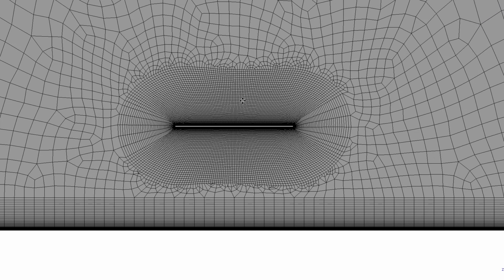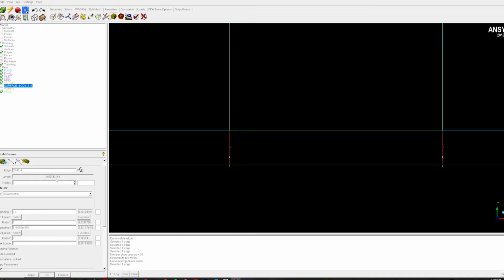identical setups. Initially, the project was using ANSYS native meshing, like with the smooth plate. With the smooth plate, this is fine on this bottom edge here, but for the LEBU, these in-between areas need to have a higher quality to simulate the large eddy breakup effect. Because these areas here were not of a high quality and weren't very refined, ANSYS native meshing would not be sufficient. It was at this stage the meshing software was switched to ICEM, which allowed much more control over the mesh.